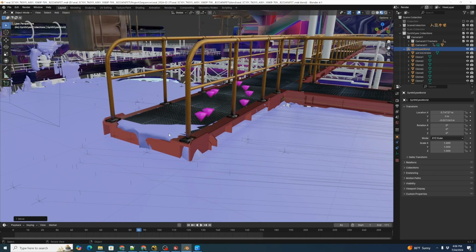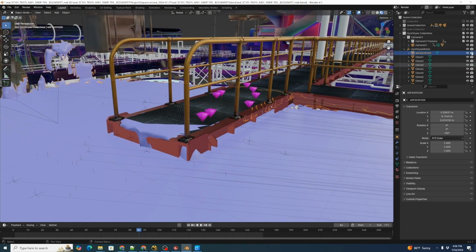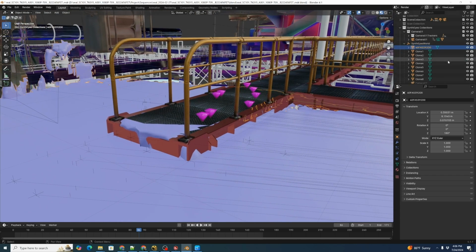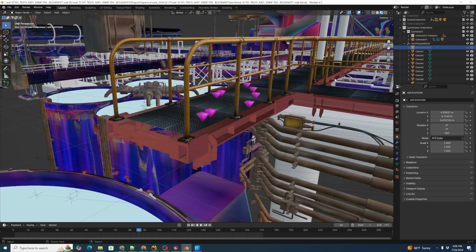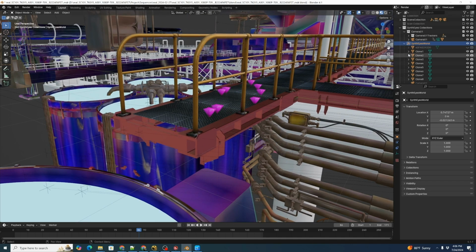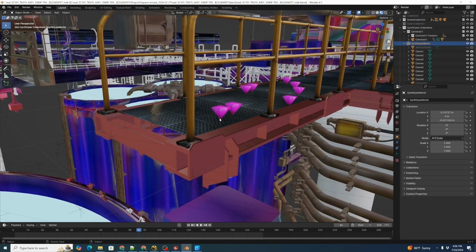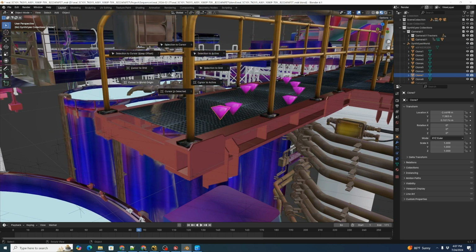The mesh has done all we need it for, so we can highlight that, come over to the outliner, hit period to highlight it, and hide it both from the viewport and from the render. And now let's do something kind of fun. This side is correctly oriented, so we can highlight that. And we're going to hit Shift S and move our cursor to our selected. And that moves the Blender 3D cursor here. Now we can actually tell things to manipulate around that 3D cursor.